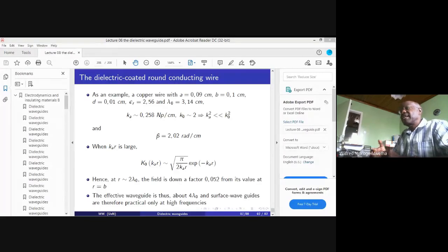And therefore we see that at the open circuited end of the guide, the electric field will try to approach the two conductors at 90 degrees, and therefore there will be bulging out of the fields at the other end. That's what we call the fringing effect. Those fields that bend so much away from the conductors will come to a point where they get detached from the conductor itself.